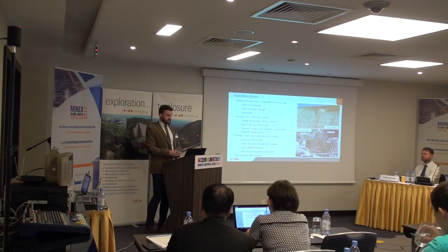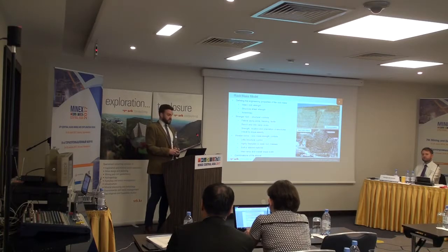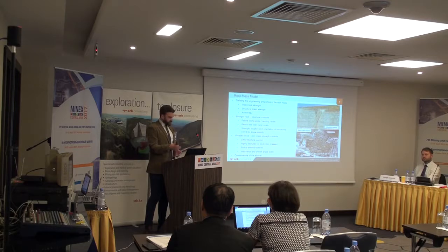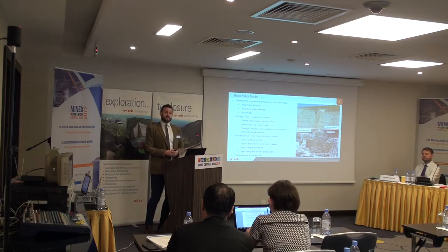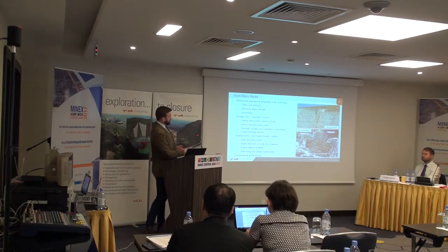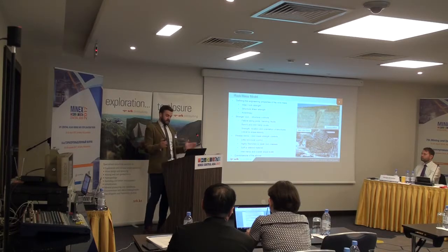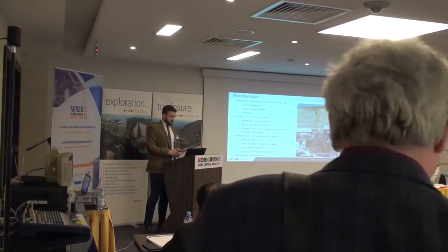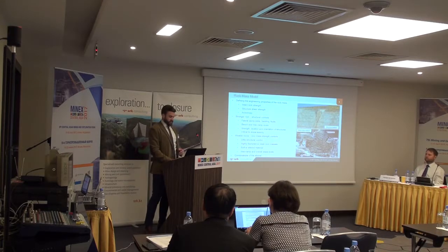And for a weaker rock mass deposit, it may not be the structures that will be used to define how the rock is going to behave, and it might well be that the rock mass strength will define how the rock mass behaves, and that needs to be considered for your pit design. So in the images here, you can see at the top we have a large structural failure in a quite high strength, competent rock mass. And then at the bottom, we have a weaker rock mass where you've got a larger failure actually through the rock mass. And you really need to understand each type of failure for your rock mass model.